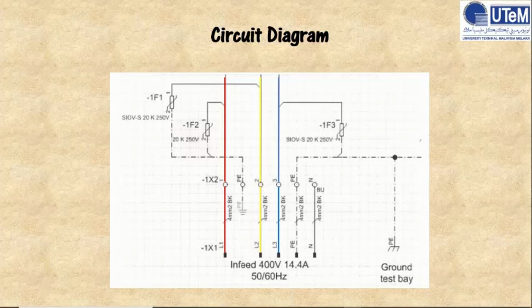There are 4 cables coming up from the internal transformer. The 4 cables will be connected to the out terminal block. The cables are 2 black and 2 yellow.